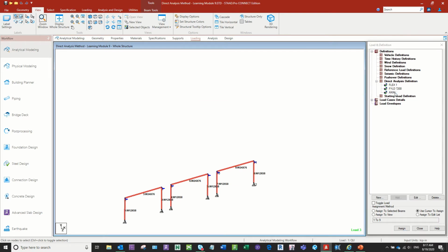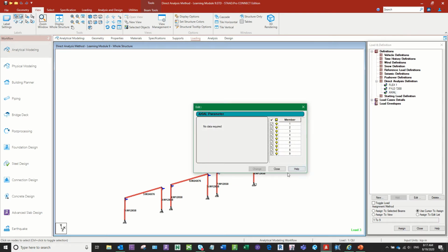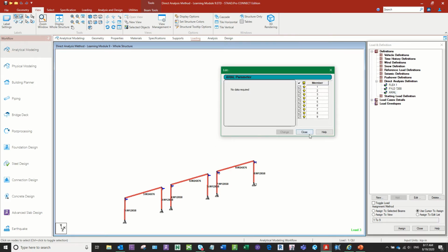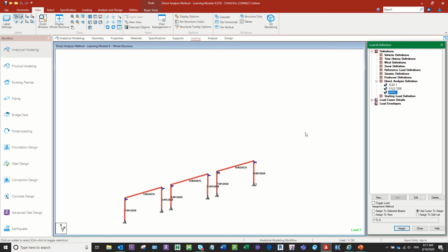Anyway, so axial also says, in terms of the other stiffness to be reduced, we have to reduce the axial stiffness as well for all of these members that are part of the lateral force resisting system on which we are conducting the direct analysis design.